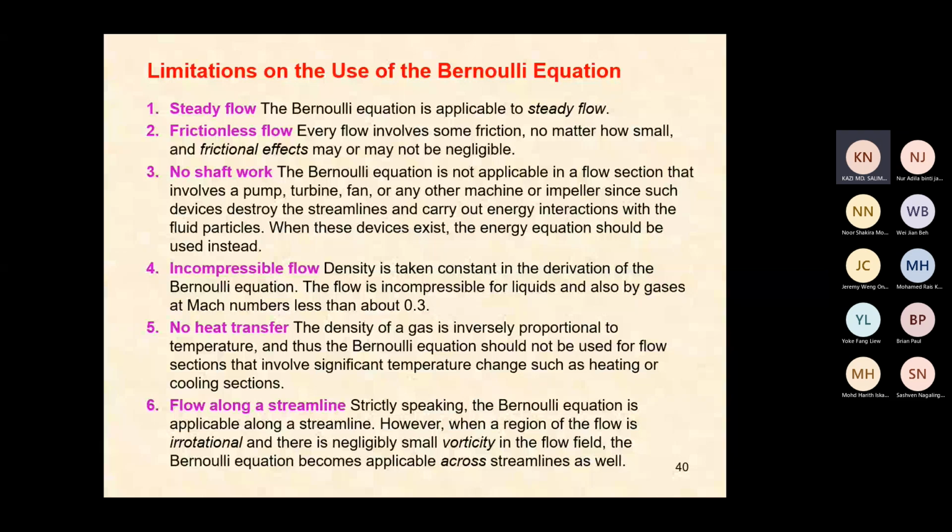And because the pressure here and here remains different, but when it is running, then it introduces energy there. So any input of energy will not be valid for Bernoulli's equation. And if you're heating it up, it will not be valid there. So in the wake region, it's not valid. It's valid outside the boundary layer.